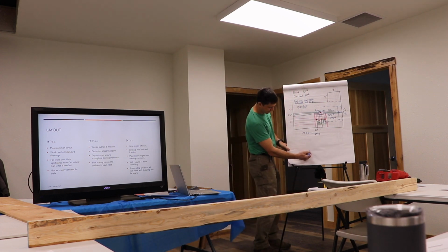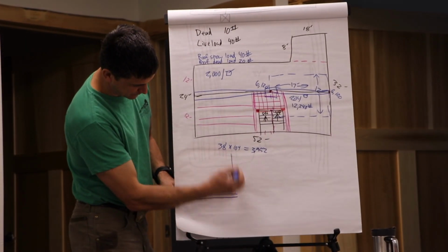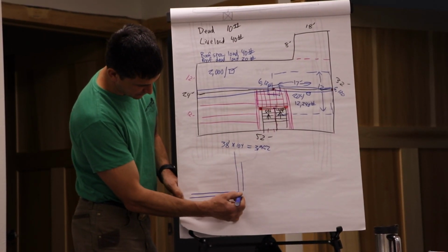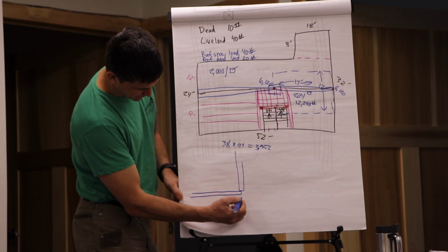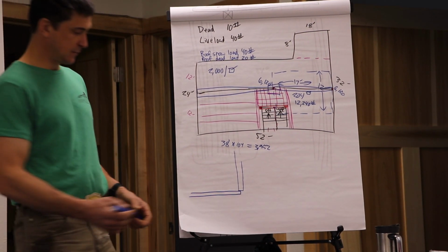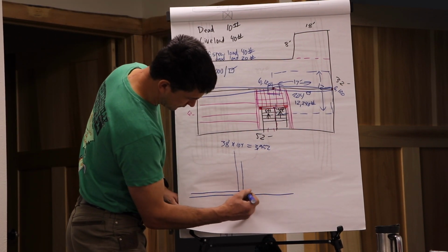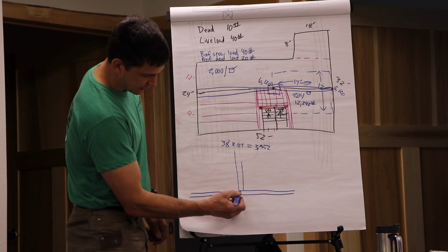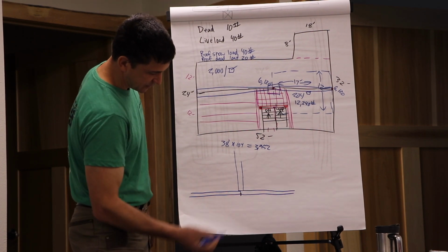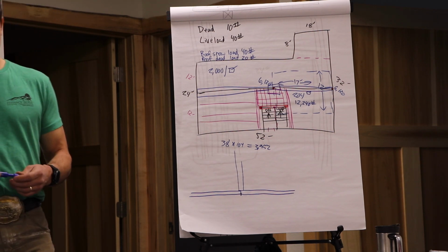So, my sill plate, my stud. So I ended it in the middle of the stud, right? So then my next plate is running this way. And so if I'm hooking my tape on the end of that, where do I start my next layout? What number? 16.